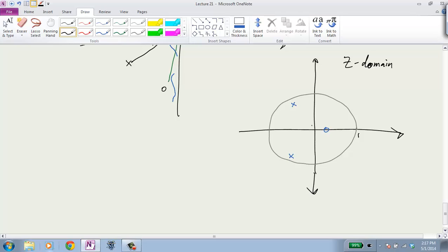All right, you're saying 3/8, yes. Okay, so you're saying basically look along the unit circle and find where you're closest to a pole. Of course, all the poles and all the zeros affect the magnitude, but if you're very close to one pole, you're going to be very large in magnitude. Okay, so that means you would expect that around here and around here, you're going to have a pretty high magnitude of the Fourier transform, and that's going to be accurate.